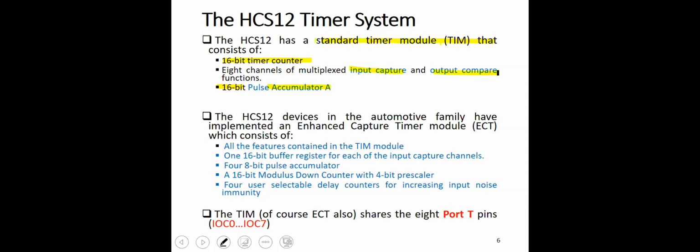You will have the counter in this module operating as a timer. So there is a timer that is running, and you have hardware that can be configured to monitor some external event on one of the pins of the microcontroller. And once this event occurs, you can record or read the current time of the timer. So that's why it's called the capture. When the event occurs, and this is an external event that is monitored at one of the pins of the microcontroller, you basically record the time and store it in some place.